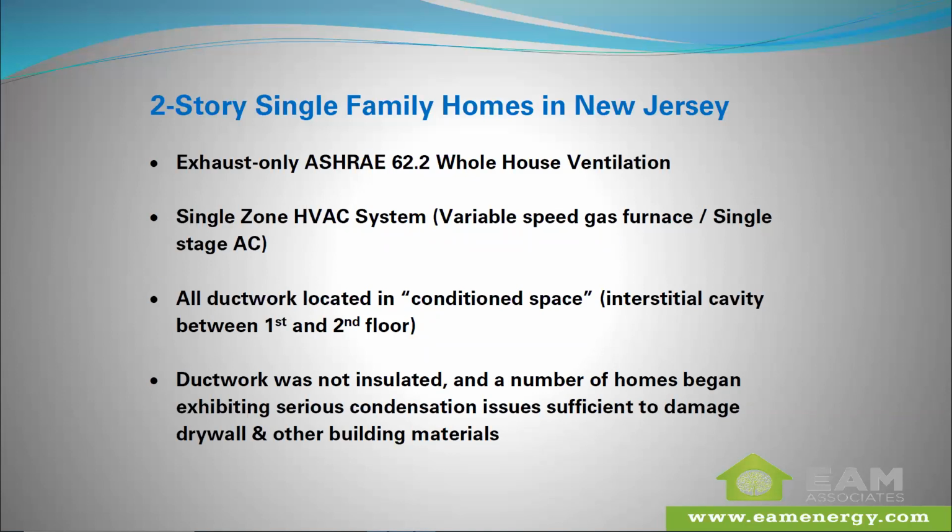The ductwork was in the interstitial cavity between the first and second floors, and it was not insulated. It wasn't required to be for code, Energy Star, or LEED. We were already part of the project, and once occupation started, the home began exhibiting some serious condensation issues on the drywall and other building materials, bad enough to cause damage.